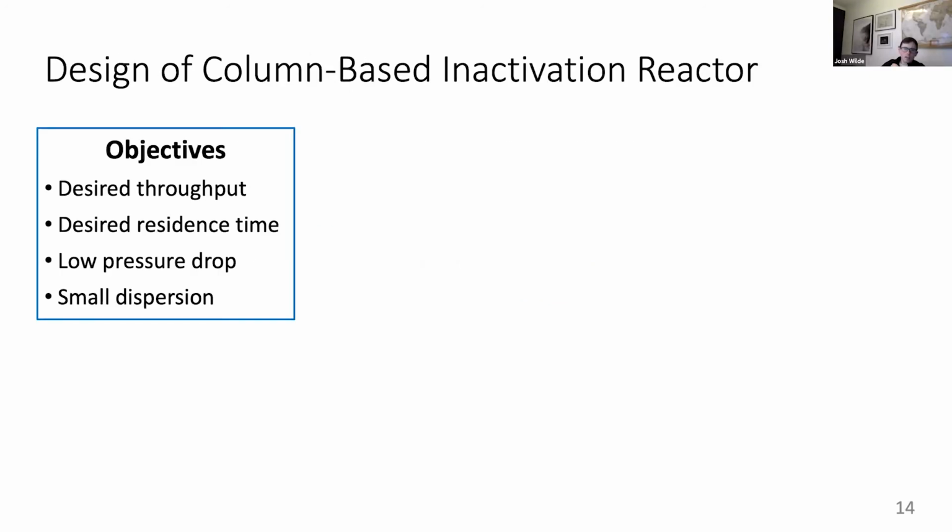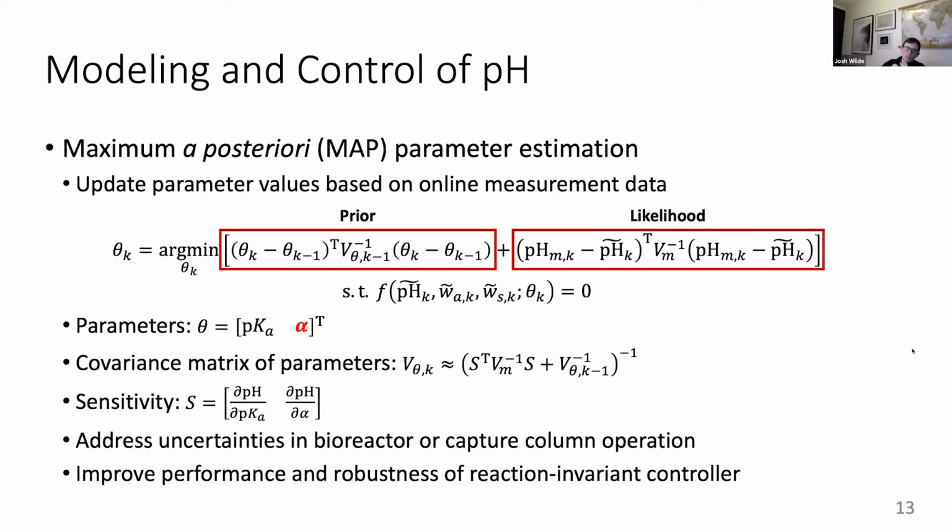Moo Sun, is that a typical strategy in a chemical engineering control problem, or is this something totally new that you guys created? So for model predictive control, the idea of having the parameter adaptation is pretty common, because as you know, the models are not always perfect. So if we learn more as we obtain data, it's very useful. But the way you obtain the parameter adaptation is different work by work. The more common method that you might be familiar with can be the Kalman filter or extended Kalman filter. But the MAP estimation is what we have applied for this specific application.